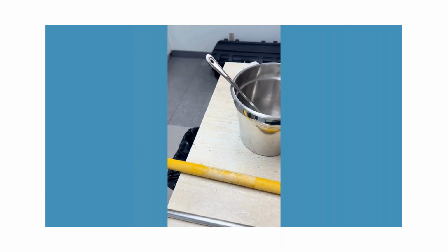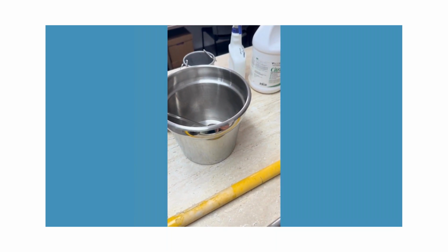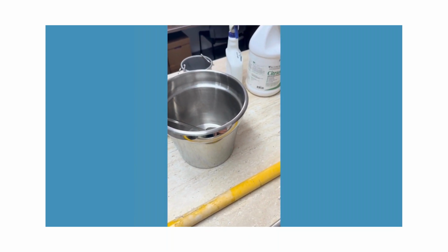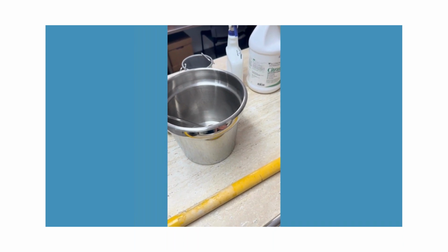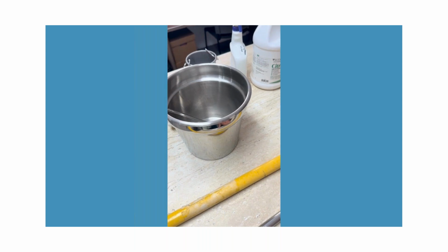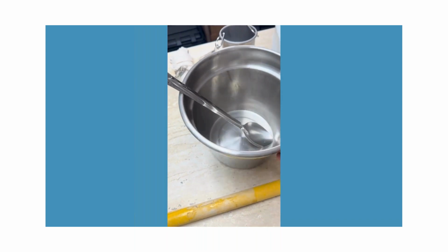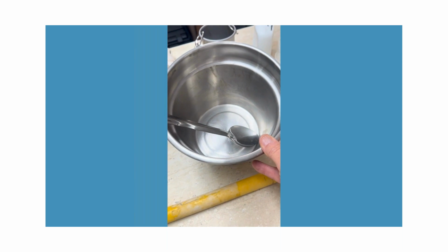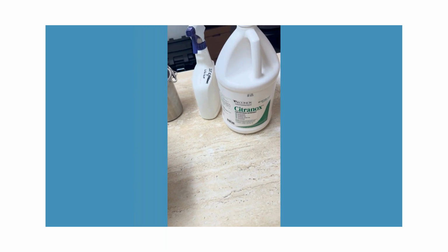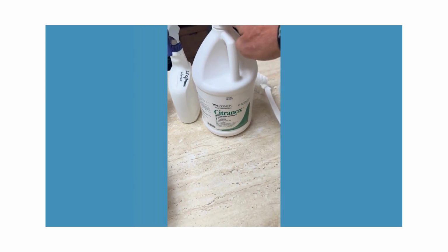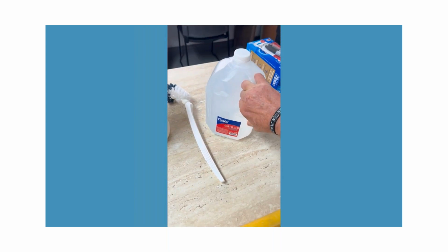You can also use a composite sampler if needed, but then you want to ensure that your sample train, which is your suction tubing, your peristaltic tubing, and such, is as clean as possible. I also have a stainless steel bucket with a scoop that I use for my biosolids composite sample. Prior to going out sampling, I clean everything with a 2% solution of Citranox and scrub it with a brush. I triple rinse with distilled water.